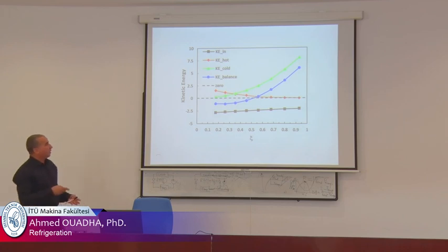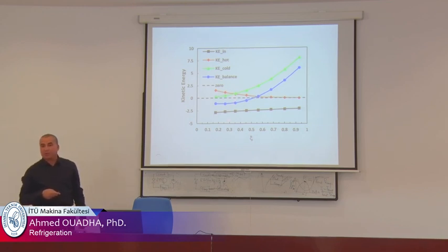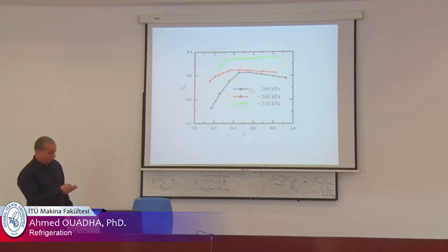And it is interesting to see here that when the kinetic energy of the hot part equals the kinetic energy of the cold, it is around 0.3. And around 0.3, we found that it is the optimum performance of the vortex tube. Here we can see it, for this one, for the red. It is about 0.3.